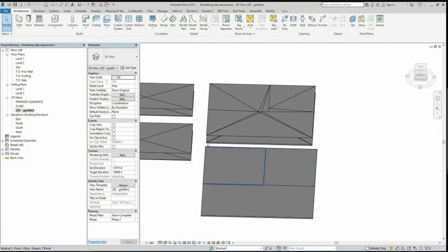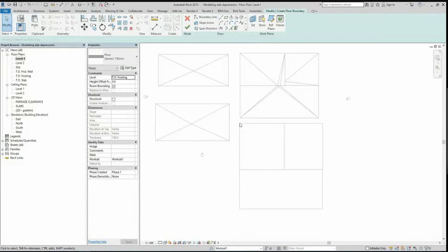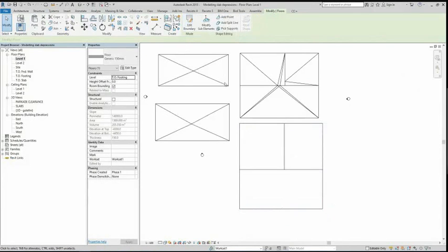to represent this overall area. So we're going to assume that this footprint of the 3 slabs is the whole entire area drain depression footprint. So what I'm going to do is create a 4th slab element to span all 3 of these, and actually I'm going to do it in 2D view. I'm going to make it the same footprint as all 3 of these slabs. And I'm going to make it 150 mils, because the important part is the top surface of this slab element, and you'll see in a minute why that's important.